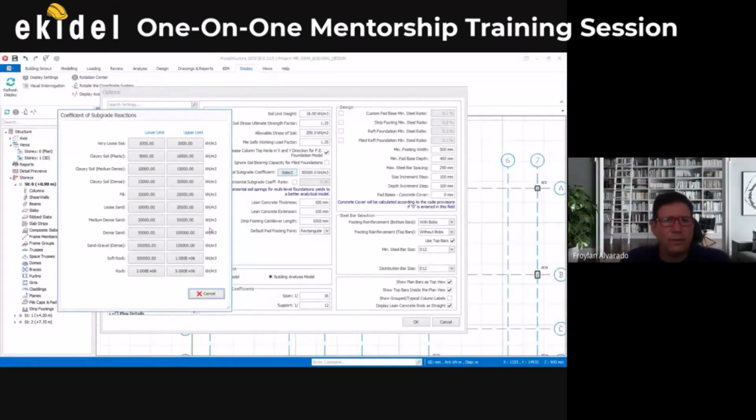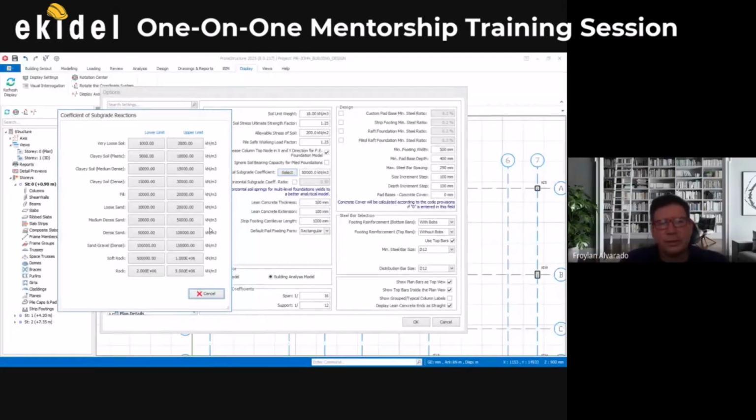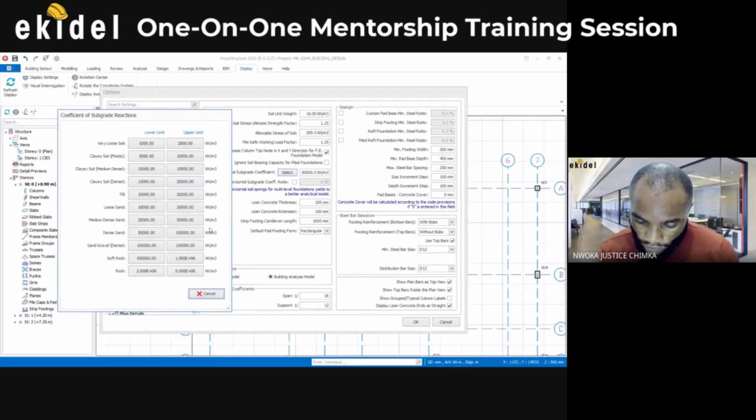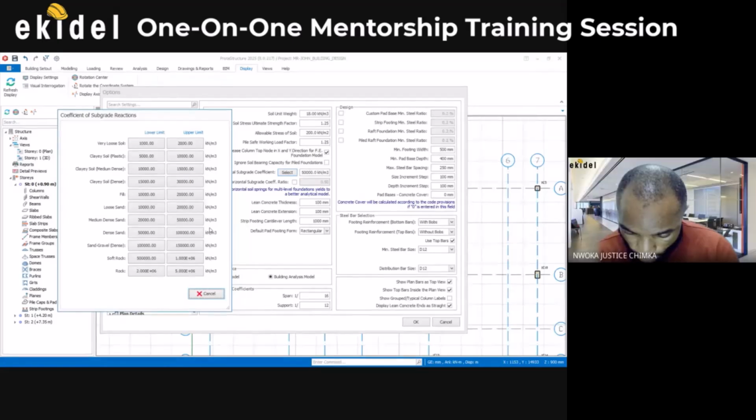If you look at the conclusions and recommendations, it says that the bedrock is about 20 feet to 23 feet below, and the allowable bearing values. What page is that? Page 8. So 20 feet of soft soil, which means really low bearing capacity.